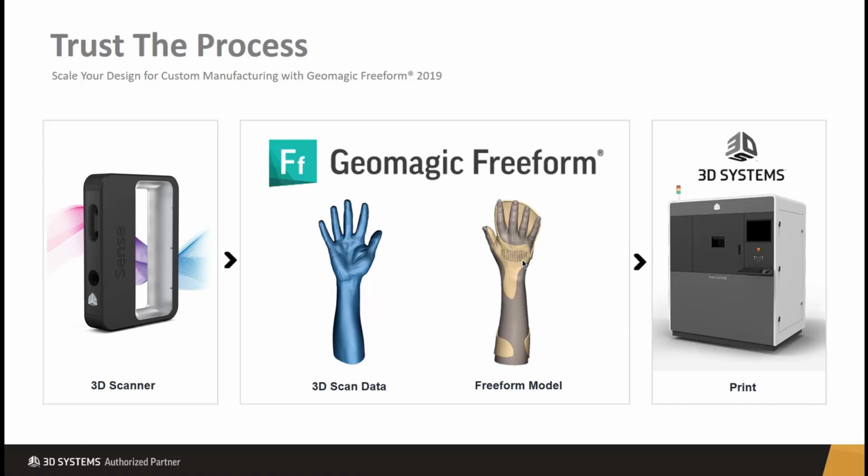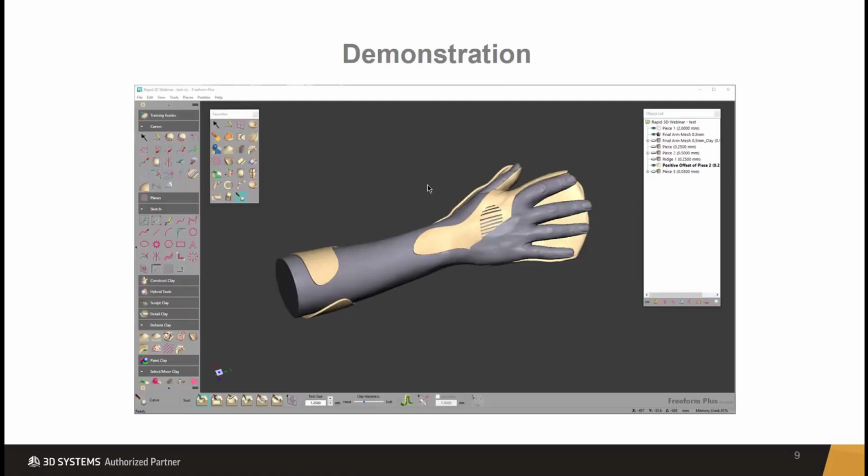So today's process is going to look a lot like this. We've captured data, and we saw that earlier, and we're going to bring in that scan data directly into Freeform. We're going to fill it with voxels. It's like pouring sand inside of that hollow shape that we've created. And then we are able to utilize a ton of different sculpting modeling tools inside of Freeform to create a shape that then we can go to additive manufacturing with if we want to. So you can see here that we can go print that object. This is an overview of that whole workflow that we're going to talk about.